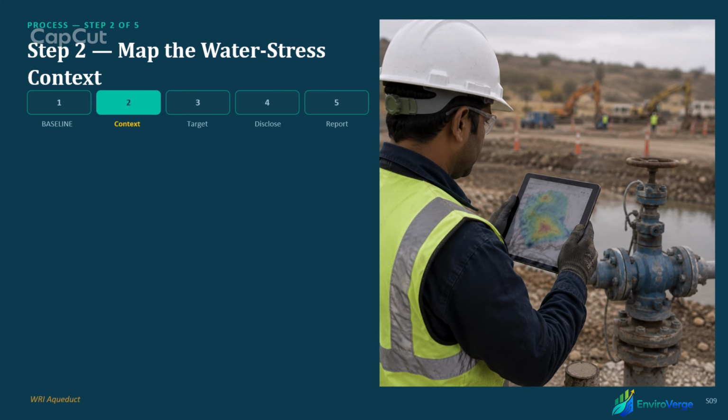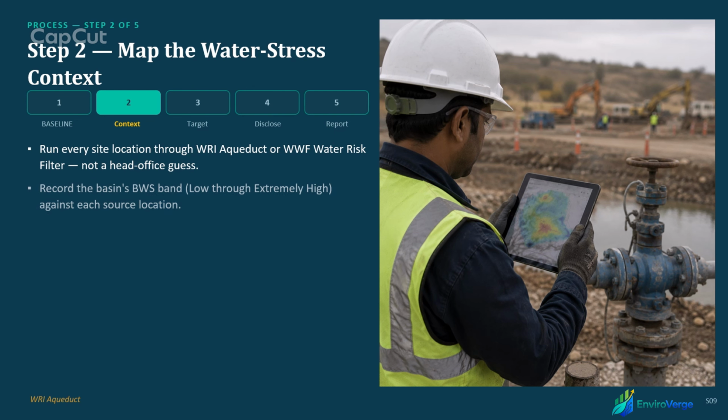Step 2. Map the water stress context. Run every single site location through WRI Aqueduct or the WWF water risk filter. Not a head office guess, not "we know this region is dry." Record the basin's BWS band against each source location individually.